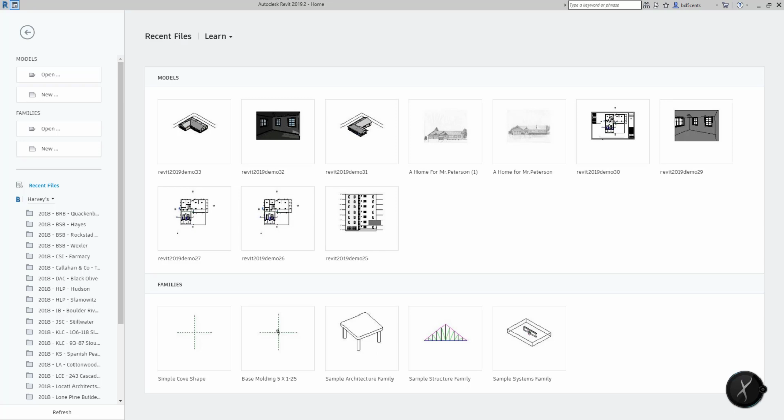Revit allows you to create modifiable families, so you have the ability to change certain selected properties like width, length, thickness, radius, etc. to meet your needs. We will create a simple table, and from here we will be able to adjust its length, width, height, top thickness, and base thickness. The strategy of family creation will be emphasized.